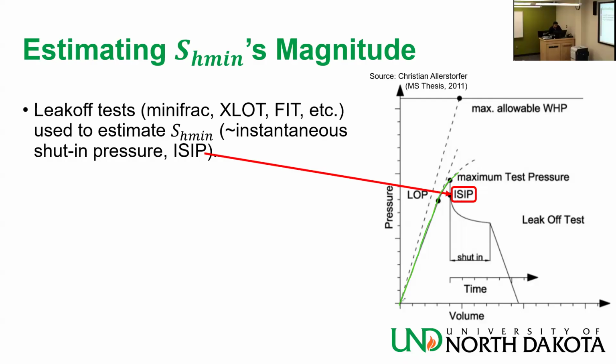Leak-off pressure. Keep going. Drop. Then if you still pump, keep going, and then switch off, it will level off like that. This part here is called unloading, removing the fluid from the well. Flowback. There are companies specializing in doing flowbacks from hydraulic fracturing.